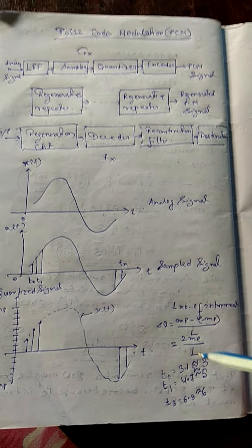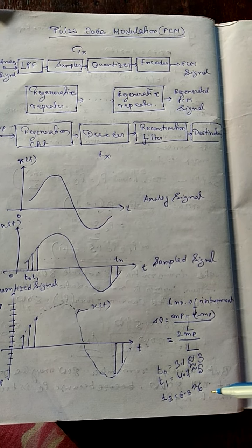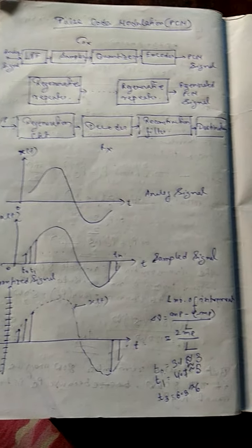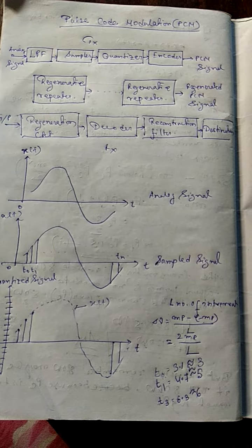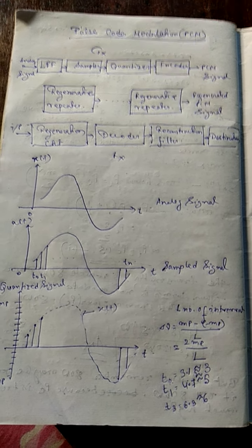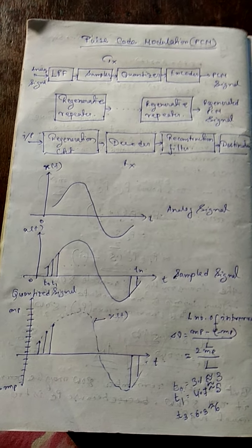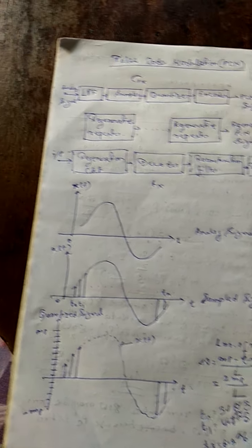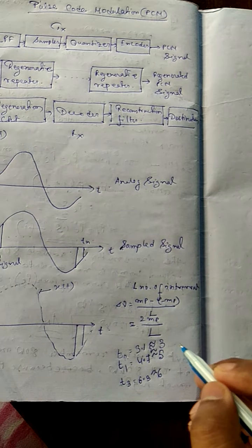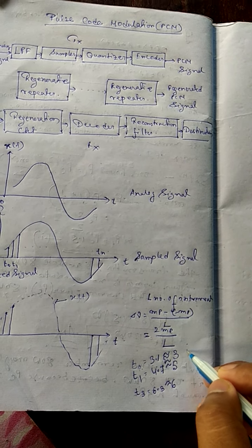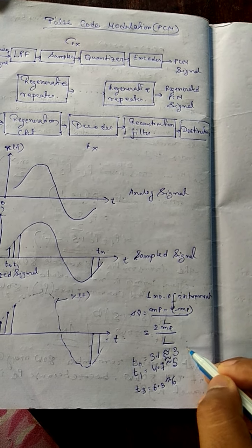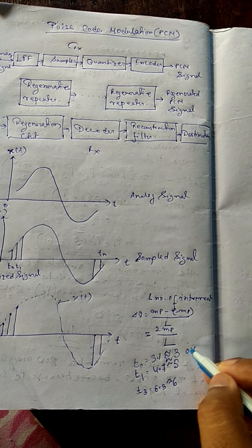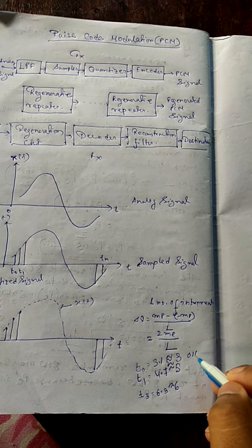One form means obviously this is the digitized form. So here 3, 5, 6 is not in binary form. And always remember, in a digital communication system we use numbers in binary form, 0 and 1, because we need only two levels of the signal. So first, 3 is 0 1 1, with powers 2 to the power 2, 1, 0.